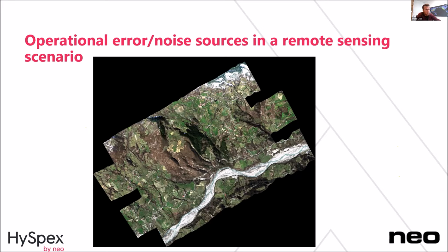One consideration for space data is that you have to have full control of how your optics change with temperature and pressure. So it's going to be different from doing the calibration in a lab than in orbit. Typically satellite systems have some onboard calibration to map the changes when it's launched, which is normal, and which we also had in our big military project, and will of course be part of our ESA EOD platform.